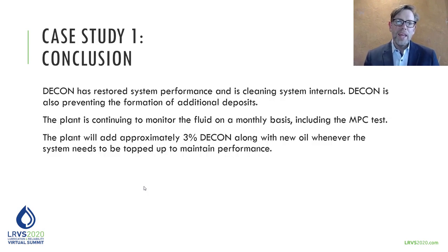A key part of this is that there's no silver bullet that will solve everything and allow you to now ignore the fluid. So condition monitoring continues to be an important aspect of this. The plant is doing regular testing and trying to do a better job of monitoring the health of the hydraulic fluid. As a top-up fluid, they are also adding the same percentage of decon to the new fluid that's added to the system to maintain that 3% level of decon.